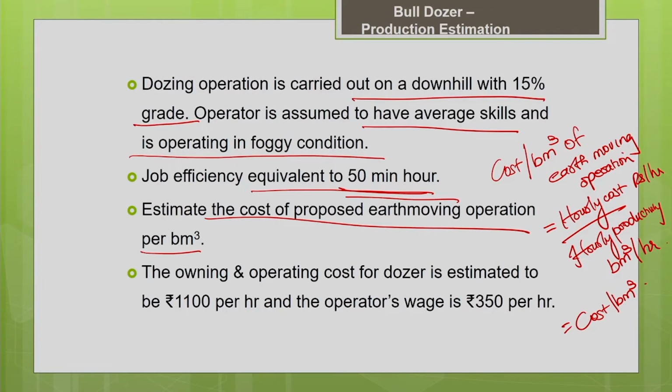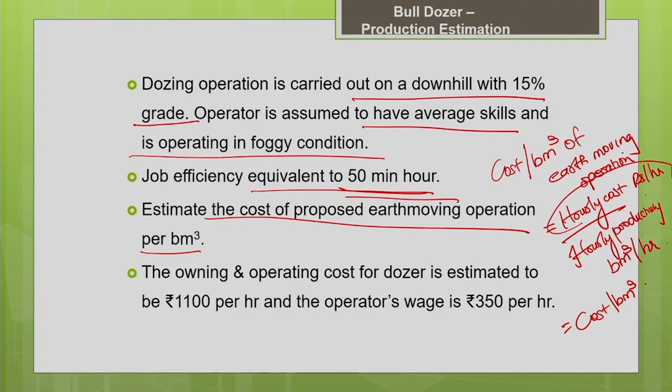This is a very important parameter which we use when you plan for bidding. When you go for unit rate contracts, you need to know the unit cost associated with every activity. We need to make an accurate estimation of the unit cost of every activity. For that you need the information on the cost associated with the machine and the productivity of the machine; that also forms a part of the unit cost.